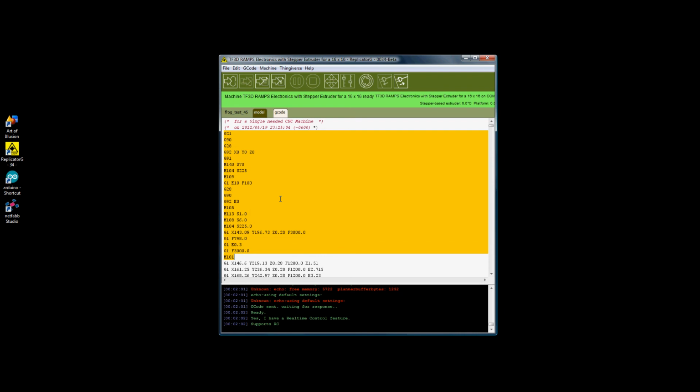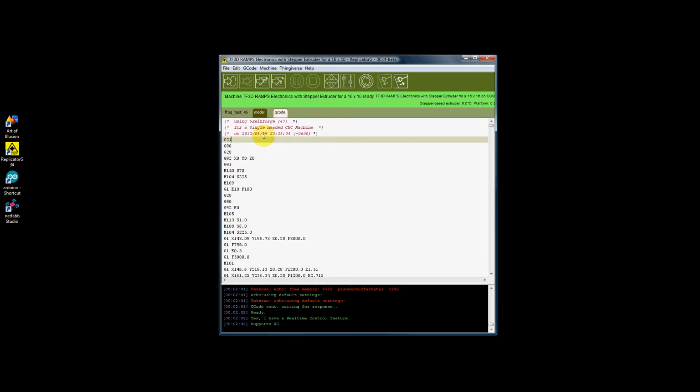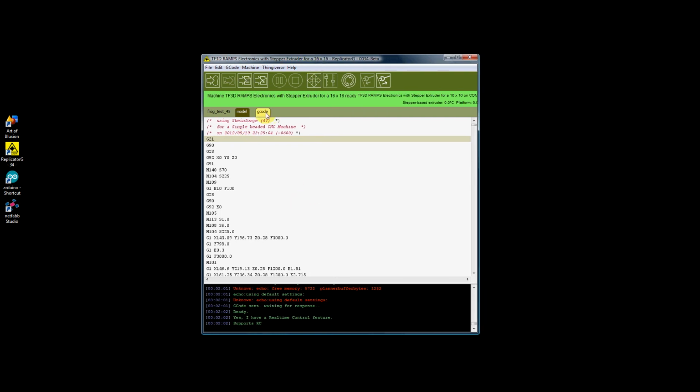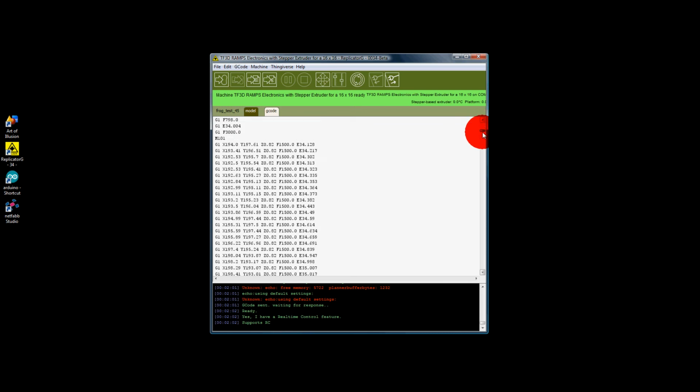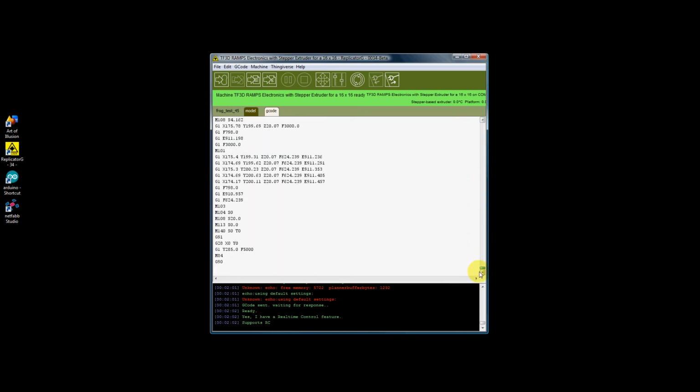Now these are all generated by start.gcode, and you can see there are no descriptions here. We've removed descriptions to make the generated G-code file smaller. If information was turned on, you would double or triple the size of your files. We've turned that off, so all you have is the raw G-code. Towards the end, you have your end.gcode, which turns your heated build platform off, shuts your temperature off, and runs through all that.